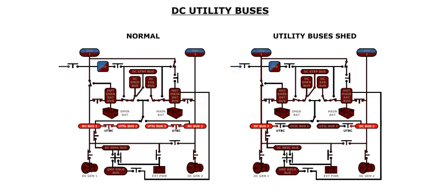Two utility buses power non-essential loads. These utility buses are powered by their respective DC bus through a utility bus contactor. These contactors are controlled by the BPCU. These utility buses are automatically shut in the event of an overload of the DC buses.